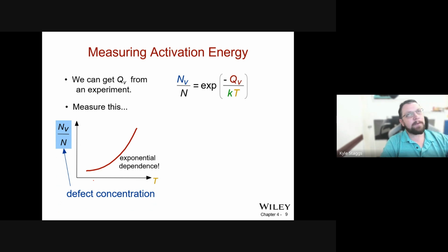Again, this is an exponential energy relationship. If we plot the number of defects, that concentration goes up exponentially with temperature. So higher temperature, higher likelihood of defects, higher concentration of defects. This is fundamentally why when we melt metals, they become easier to form into new shapes. This is the mathematical necessity behind that operation.